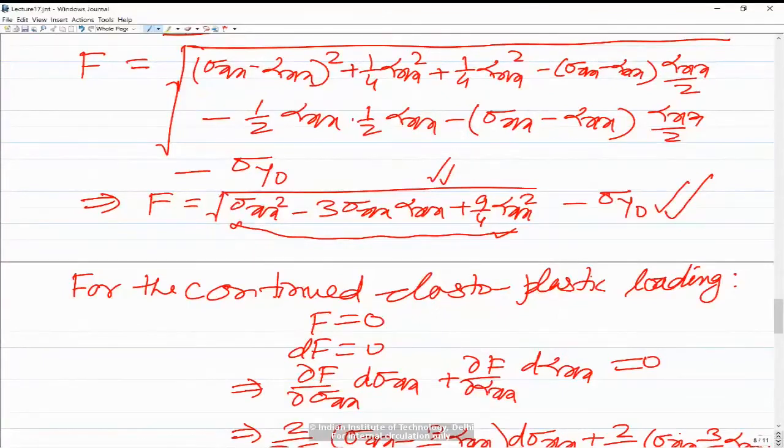Sir, we also have to define the tolerance, no? Yes, we have to define the convergence criteria. You can put the convergence criteria either on stresses or on the displacement, so that the difference in the stresses between two consecutive iterations should be less than a certain tolerance. In software, when we give input for nonlinear analysis, force tolerance as well as displacement tolerance come into the picture.